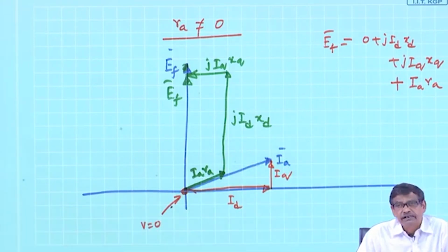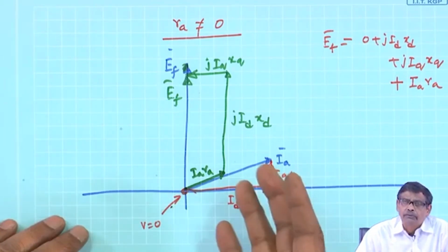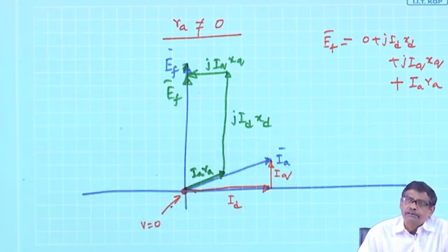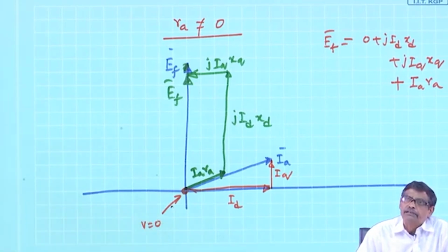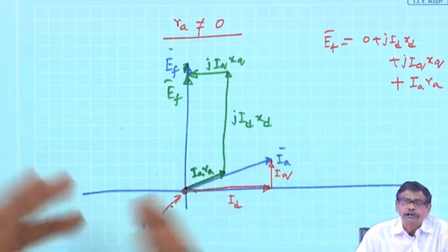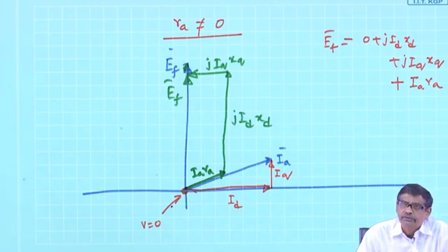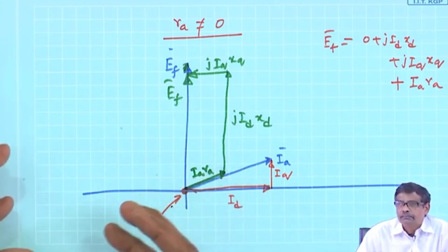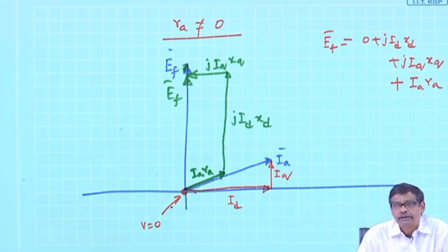Then I took up the single phase induction motor. The analysis of the single phase induction motor was based on the 3-phase induction motor only, although it is slightly involved, because I showed that a single phase induction motor develops a pulsating field which can be broken up into a forward and a backward field. Therefore, those two induction motors can be used individually, as if positive sequence and negative sequence components are 2 individual machines; find out the torque from each and take the difference.